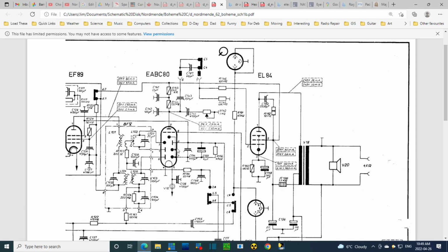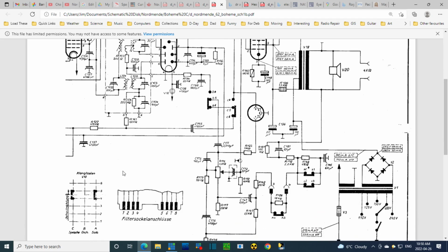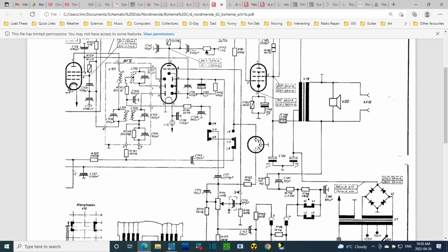I'm thinking now probably this one and this one are combined to produce the FM detector. And it's a ratio detector based on the way these diodes are. And then this would be the AM detector down here, hooked up to this coil, which is the last AM IF. So the AM audio is coming out here along with some voltage. The DC voltage is not going that way, it must be going this way. We're on to the other page. So we have a line, and a line.